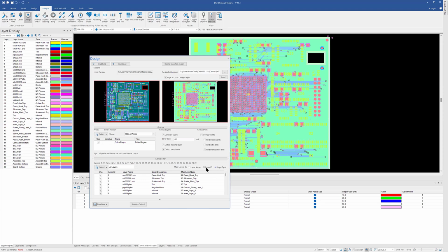It's doing it by layer type here. You have other options: layer ID, that would be the order, but that doesn't really work for this data set, looks like because we added the outline layers. Or layer name, but they're completely different layer names. Now, you can always map manually if your layers aren't able to combine here so that we can do this comparison. You can see which layers are going to be compared here. If there are any that didn't get listed, I would just manually add them, but then I would simply run this.